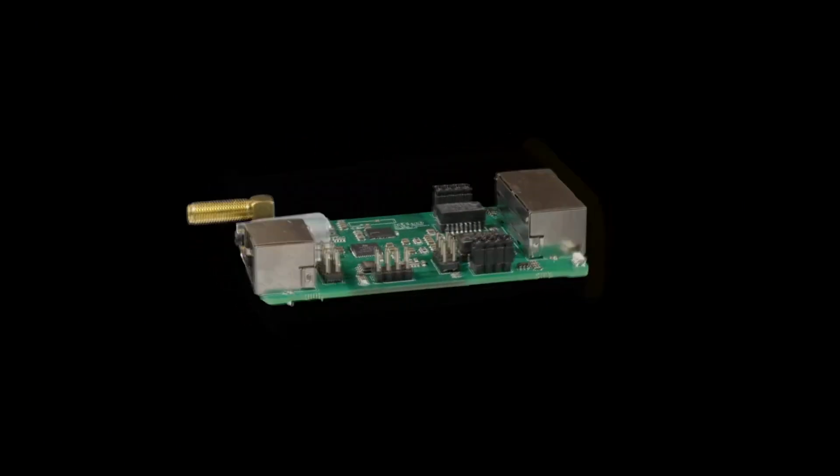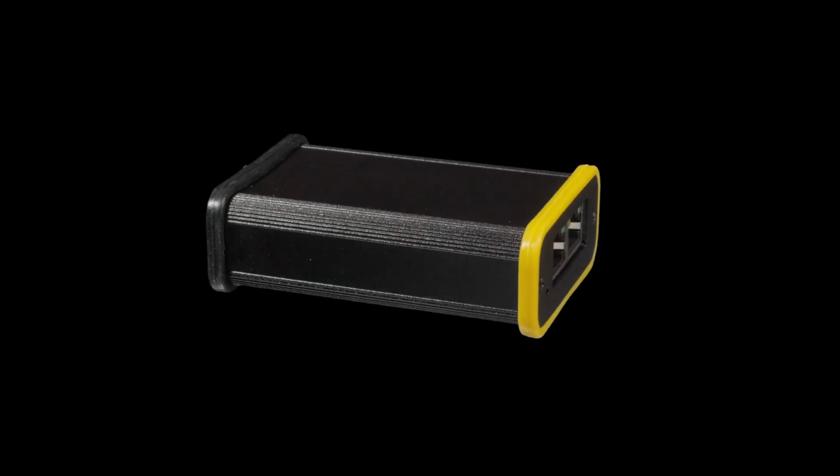And finally, the RJ45 connector on this side is reserved for future extension and isn't actually connected to anything yet. There are internal headers that allow to connect small daughter cards for whatever extra hardware is needed, but currently none have been designed or implemented. Some ideas were RS422 interfaces to implement GPS module emulation for the RBS 6000 BTS, or some GPIO to control or monitor the environment, or things like that.